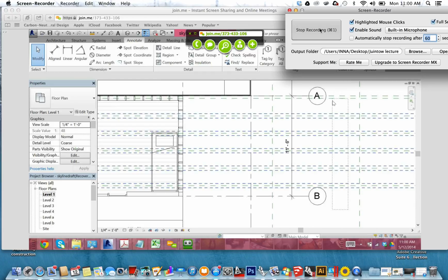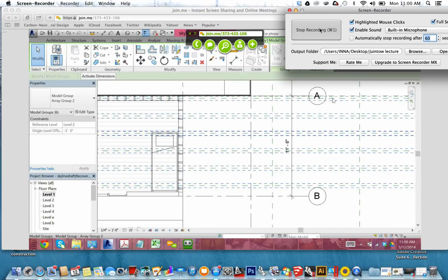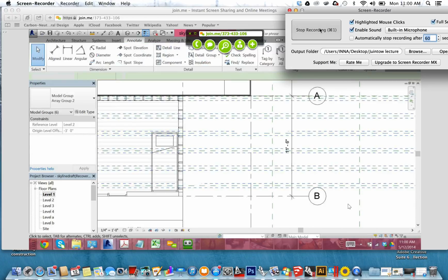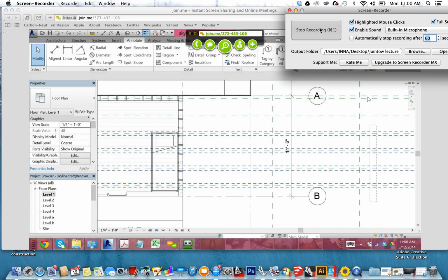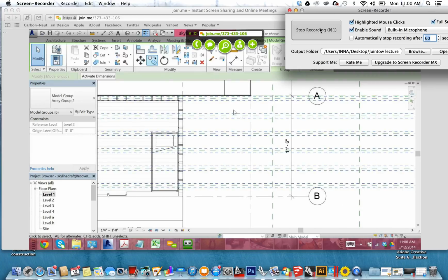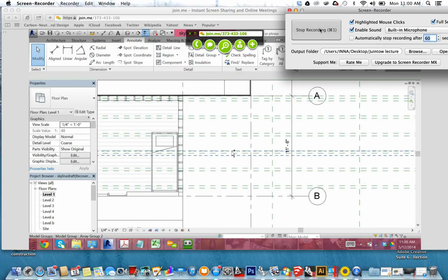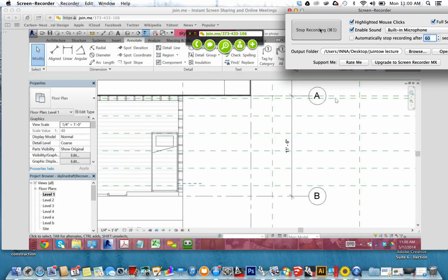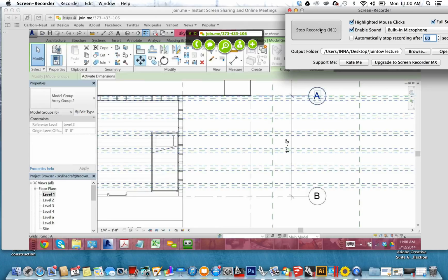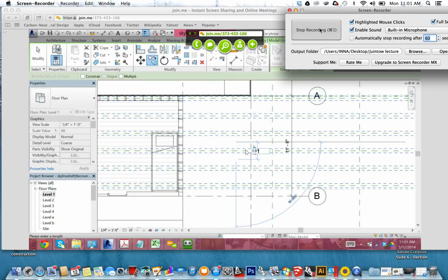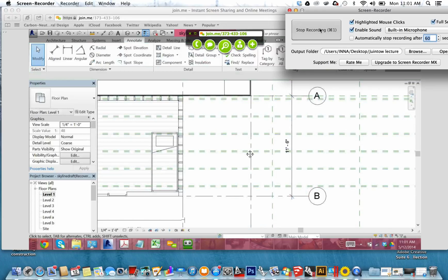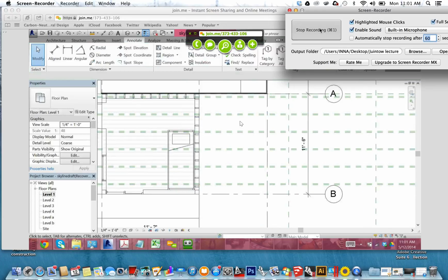And then let's just say that those reference planes need to have some thickness to them. So let me just copy those guys down. And I just bring it down, and then I start typing 3.5 inches. So that's either side of, oops, sorry, it should go down 1.5 inches because the 2x is 1.5 inches. So I come down and I go 1.5 inches. So that's either side of my stud, okay? Those are the reference planes. Got that?